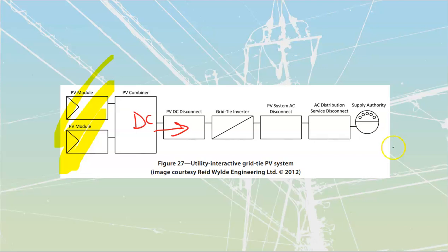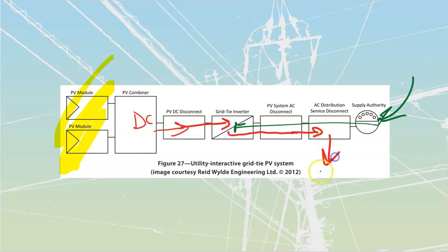What that grid tie inverter is doing is it is always monitoring what I have got over here from BC Hydro. So BC Hydro feeds in, and I'm just going to monitor the voltage over here at the grid tie inverter. I'm going to watch that, and I'm going to take my DC and synchronize it to that as I convert it into AC. And then I pass that AC current out to my service disconnect. From there, it goes down to the loads. They don't show the loads off of these ones over here, but it's going to pass through to my loads. And if I've got any extra, I can sell it back to BC Hydro, because the synchronized power can go back out onto that grid.